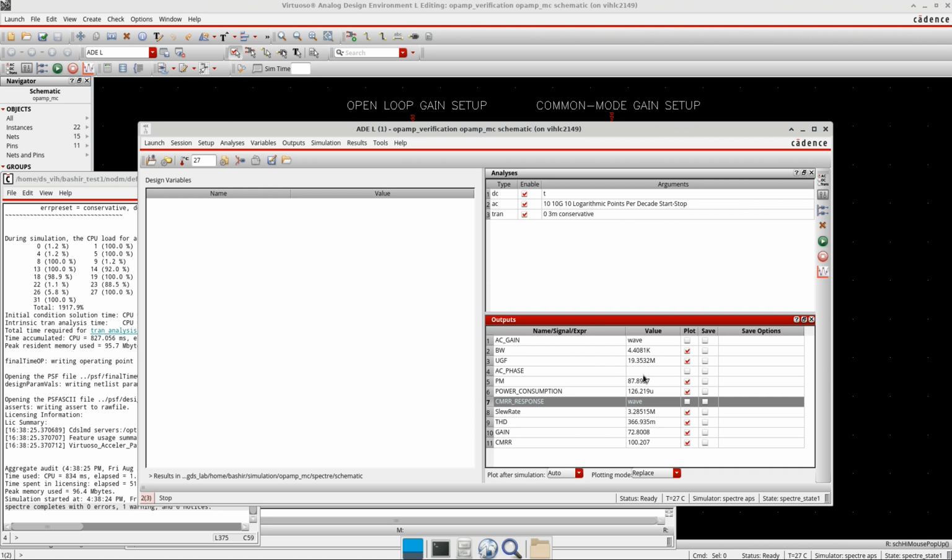So before actually doing the Monte Carlo simulation, you need to define the model library, which contains the models which could predict the statistical variations from the device and the model parameters. So when you use these model libraries for the Monte Carlo simulation, it allows you to predict how the impact of the mismatch or the process variation is going to affect a single chip or a wafer, between different devices.